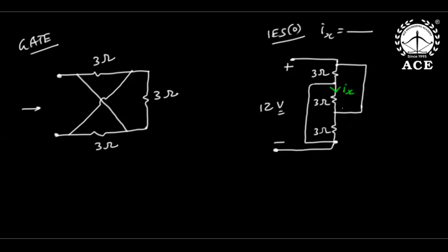Okay, everybody listen now. What is the resistance in here? It looks confusing, so I do node shifting. This junction is A, and the same wire is also A. This junction is B, and the same wire is also B. So finally there are only two terminals, A and B. One A to B, 3 ohms.